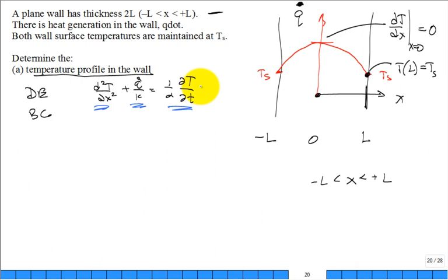Well, do we have a transient problem? There's nothing in this problem that says it's transient. Everything says it's steady state. Well, it never does say explicitly that it's steady state. Then assume it's steady state, because you can't do anything without making that assumption. So if it's steady state, boom, that term is 0.